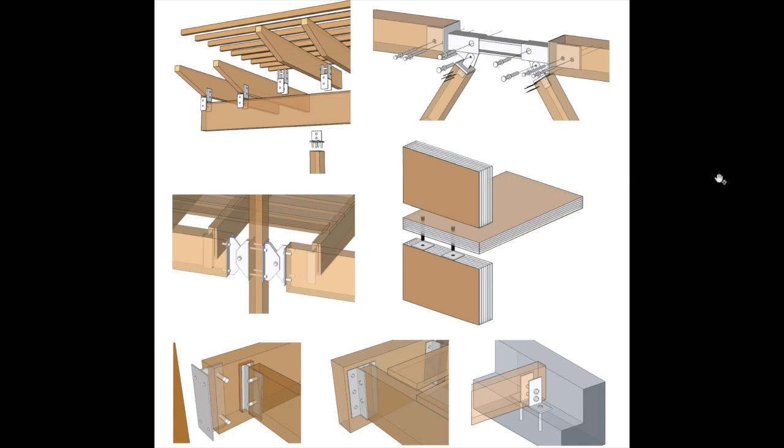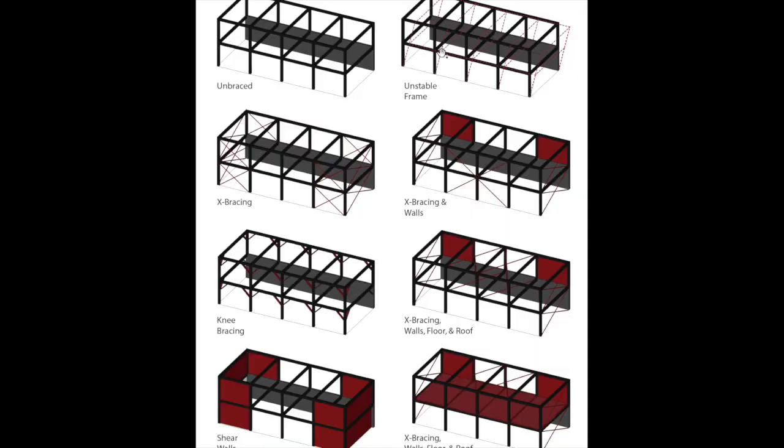Making choices about our connections then is another aesthetic choice. So either the purlin to the girder is something that's hidden or exposed. Hidden here with exposed, how it rests on the retaining wall. If we chose to use CLT, how those would be doweled together, whether we choose to expose these with steel, whether we layer these or whether they're coplanar, and even how we start to use things like diagonals to brace it. Because of course this is one thing we haven't solved yet.